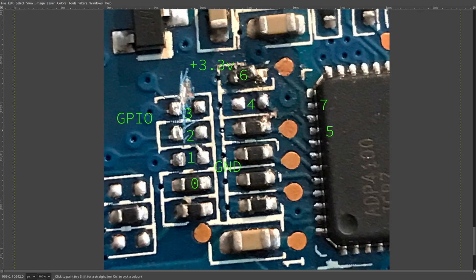And then the other side of your switch will go to 3.3 volts, which is either here, this is the 3.3 volts produced by the controller, or there's also 3.3 volts there. Doesn't matter which. VID 6 here, by the way, is connected just directly. So it goes something like this, and then it just connects directly to 3.3 volts. So if you desolder this, you get 0 volts on VID 6.